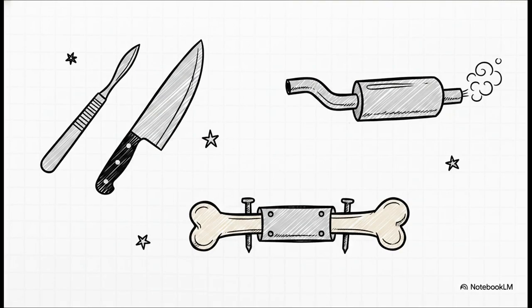And this is a brilliant example of how just tweaking the recipe a tiny bit further gives us entirely different classes of stainless steel with wildly different applications. We've got the Martensitic class, which you can heat treat for extreme hardness, making it ideal for things like surgical tools and premium cutlery. Then there's the Ferritic class, which you'll often see used for automotive exhaust components. And finally, the Austenitic class.